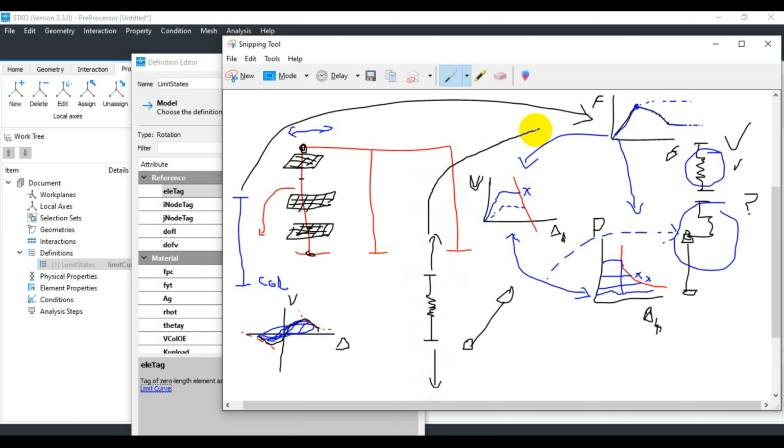That elongation can be represented in terms of stress-strain, which indirectly is the definition of the material that you are using in the element here. So it's kind of checking the performance based on the available information. Similarly, if you want to check the strut-and-tie mechanism, or the compression-tension behavior, you can use it in your analysis as well.